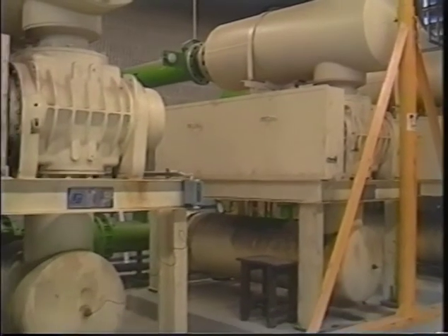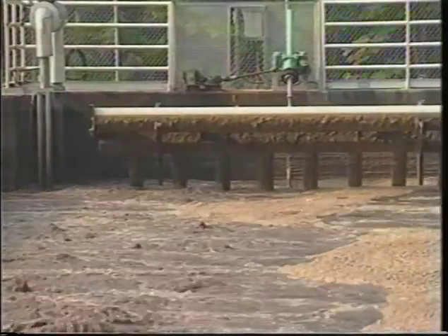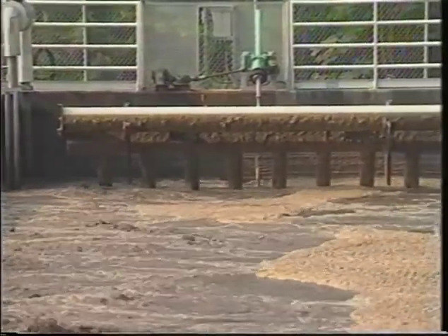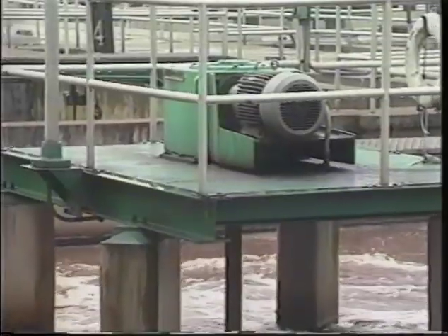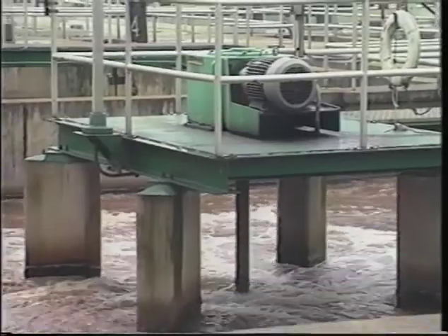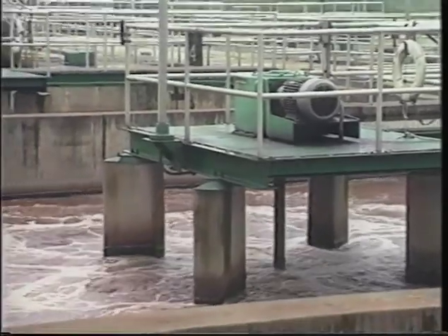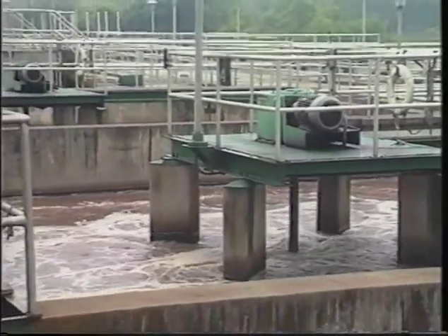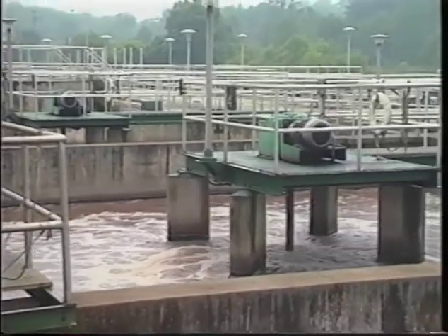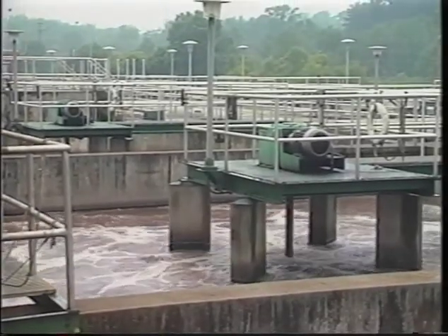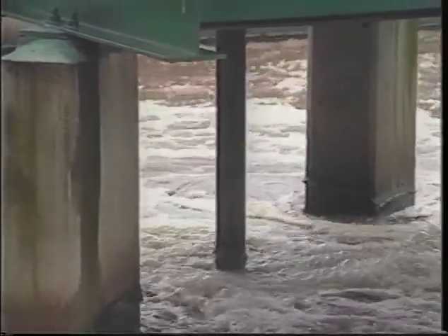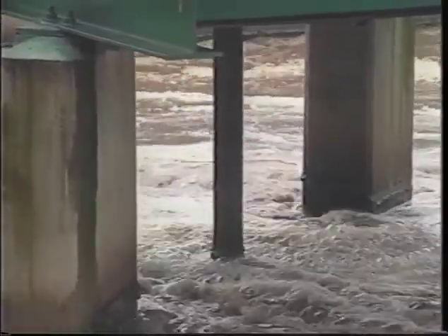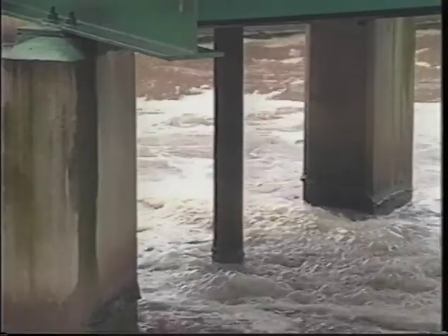Air diffusion systems in an aeration tank may be designed as coarse bubble or fine bubble diffusers. Some aeration systems may use a combination of mechanical mixing and diffused air. In any event, with either mechanical or diffused systems, the purpose of the aeration system is to transfer dissolved oxygen into the mixed liquor and to thoroughly mix the contents of the aeration tank.